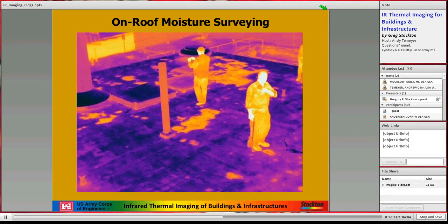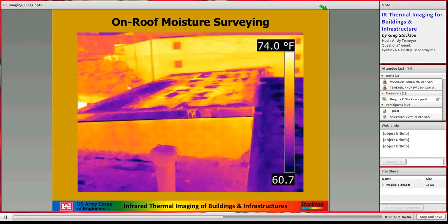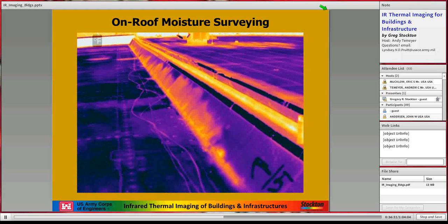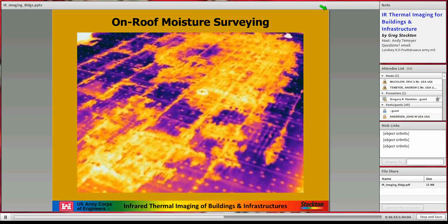Same kind of picture right here. You're looking for the heat coming through, and you're seeing the little black cold spots. On roof, by far the most popular way to do infrared is basically you wait till it gets to be night, you wait for the substrate to cool off, and it leaves these amoeba-shaped areas and whatnot, and then you take a paint can and you mark the roof where it's wet.